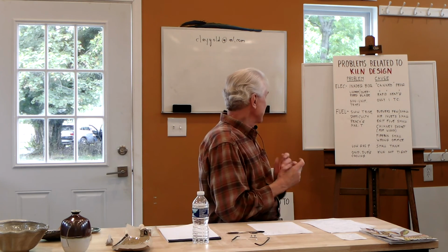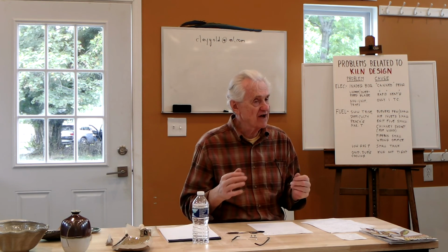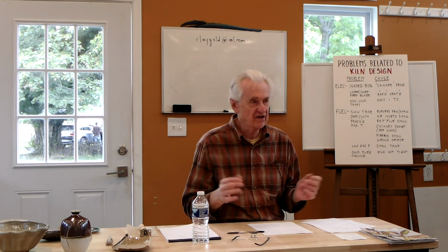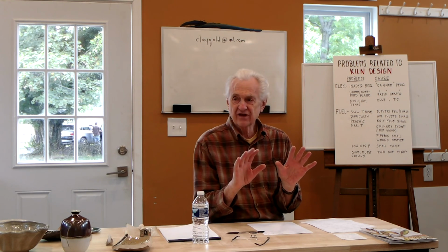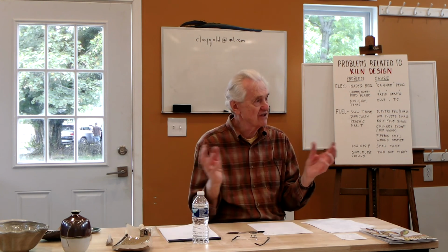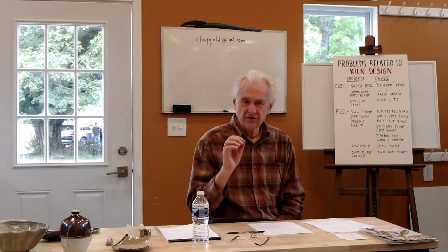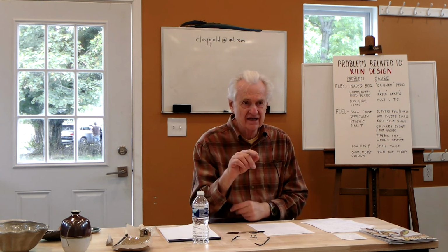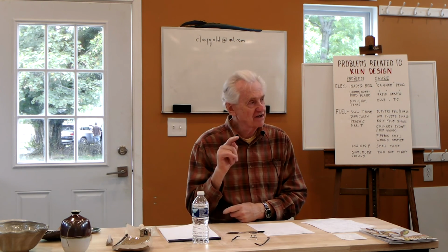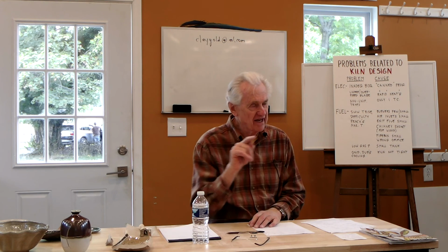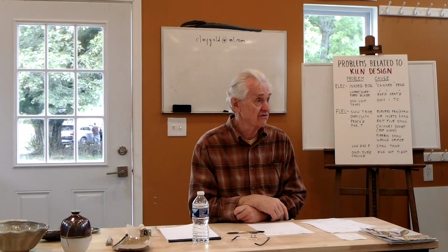And finally, the last one I had here is oxidation during cooling. When you finish firing the wood kiln or the gas kiln, you want to shut up the kiln completely tight and not let any air in, because as the kiln cools down, it will tend to draw air into the kiln. If there are particular holes or spots where air can leak in, and they happen to lead to a pot, you get a little jet of air or a stream of air hitting a hot pot, and it'll reoxidize the glazes.